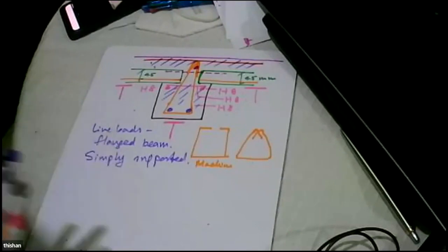So because of that reason, without a major error, we can say the whole system can be designed for the ultimate loads, considering that the precast system and in situ cast, everything has been cast in one go. Is it a clear argument? Yes, sir. Argument is clear.